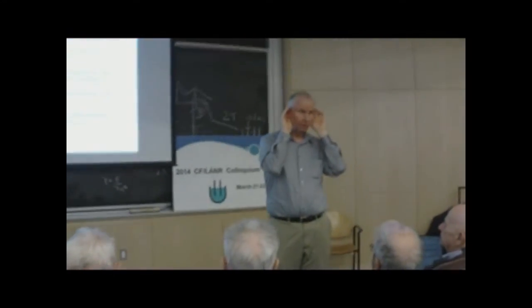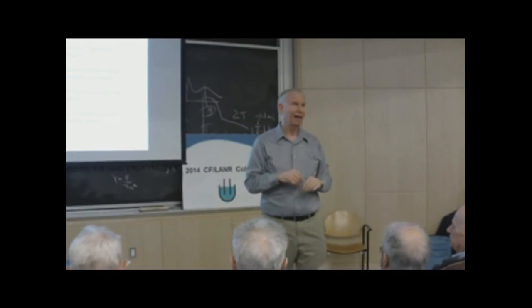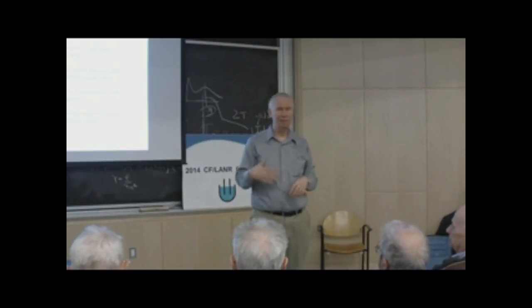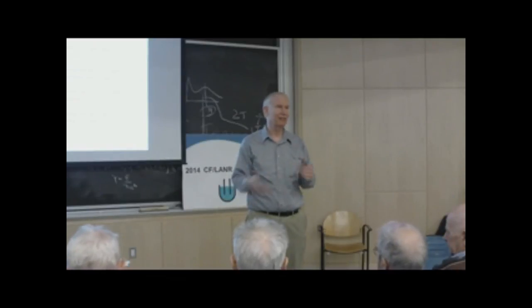This linking back to this fission mechanism. Is this really correlated to hydrogen embrittlement? We actually have very high pressure in the metal, and either by galvanic reactions taking place, or loading of the hydrogen in itself, and then creating these effects. Hydrogen embrittlement is sort of this topic that's been studied in conventional electrochemistry and corrosion material science for a lot of years.